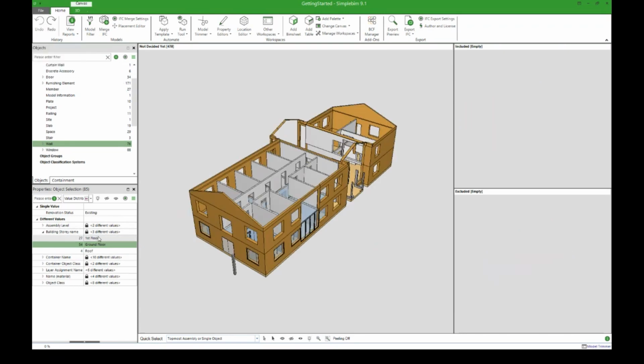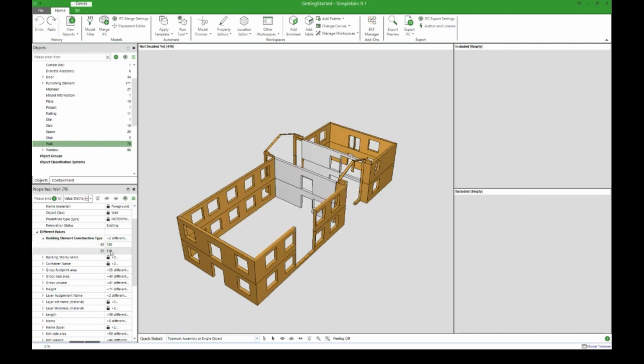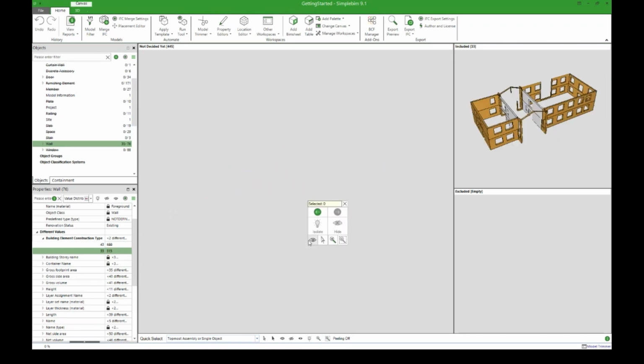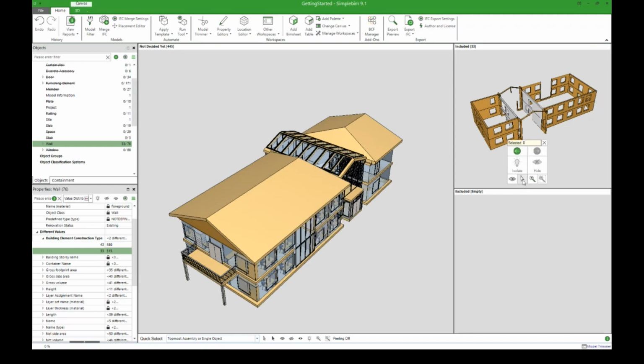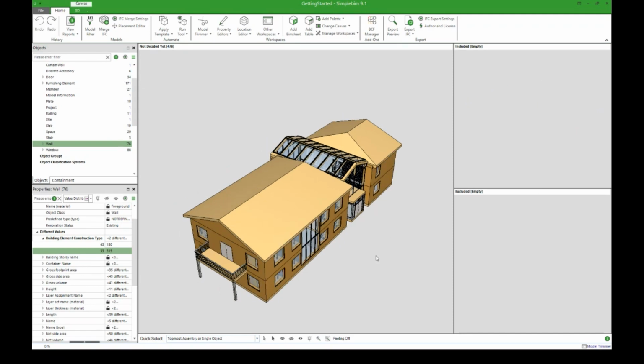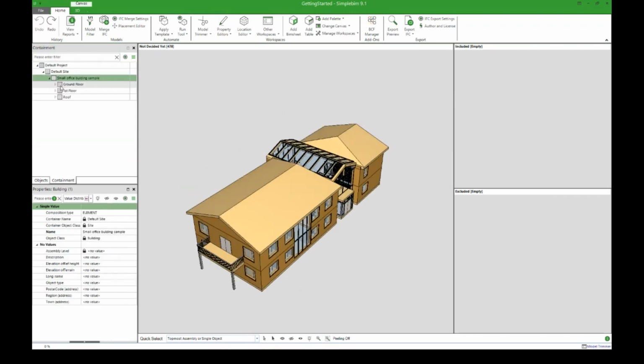So it's also possible to select this kind of things by property value. This is automatically grouped. So selecting this is selecting all the walls of this type just by clicking on the value. And then I can do the include here. Okay. So it's good to know that you can do selections in many different ways. Even in the containment, everything in one building story selected like this.